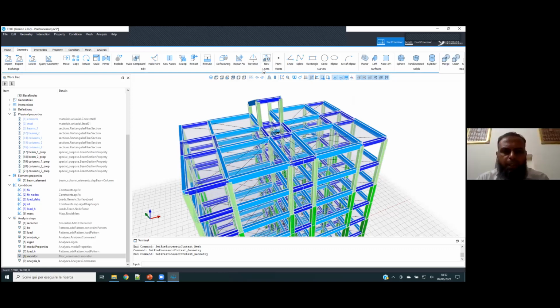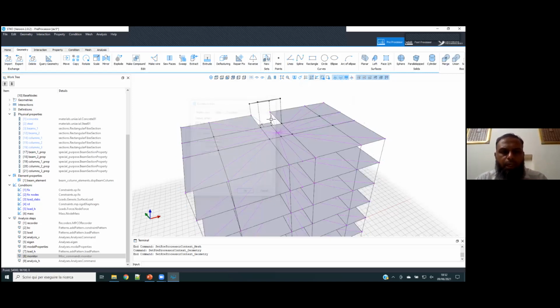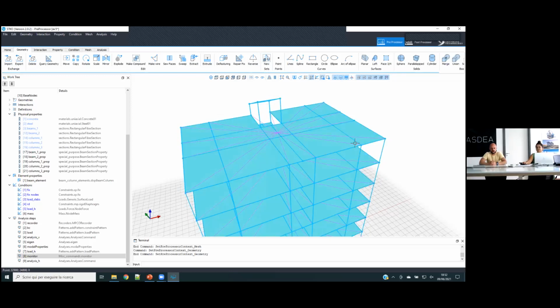Okay, let's say now I have made this model. I have copied this model on my computer. Now, can I edit a node? Can I shift its position? For example, if I select one node and I want to change its position from the graphics. Yeah, actually, it really depends. You can change a geometry, but you cannot just move a node and expect the geometry to change, because that node is the boundary of a surface. So you have to change your model. You can move an entire geometry, but not a single node of a sub-geometry. If you try to do it, you will not manage. I select this node, I move, I try to reselect the node, nothing will happen.